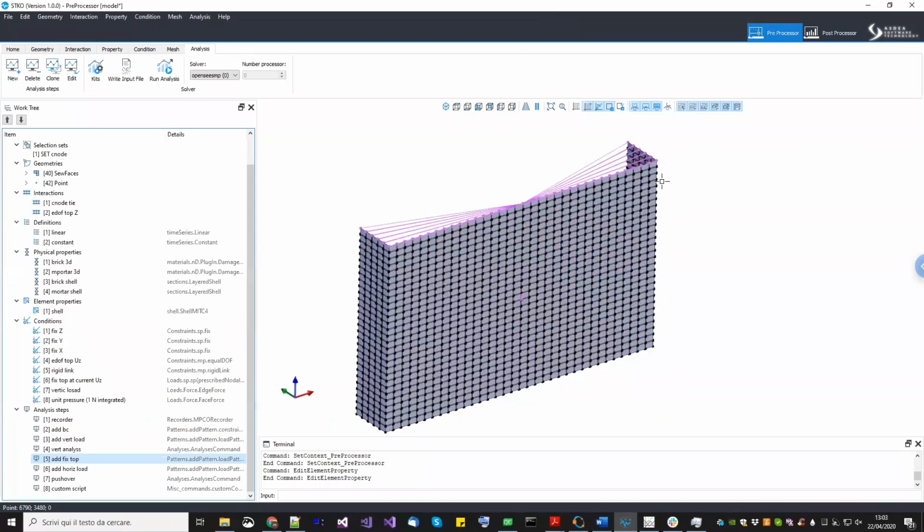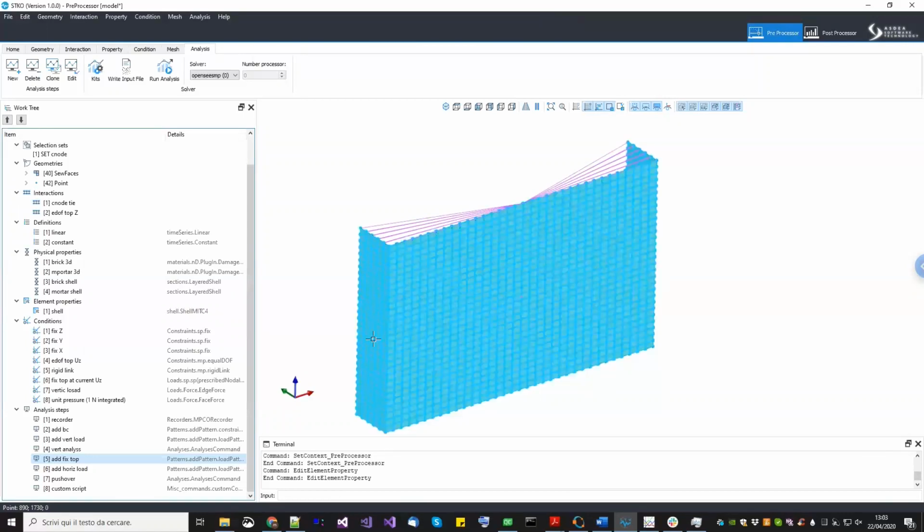Now, since we realized that in this example, even if the overall failure is in out of plane bending, the local failure is in transverse shear. Now, as you know, material models such as frictional materials, such as the one that we use in the mortar, have the phenomenon of dilatancy. So when it is loaded in shear, it uplifts and creates an apparent increase of volume. What's the problem is that in this case, since the vertical displacement is fixed, while the mortar joints are failing in shear, they would like to uplift the wall, but the wall cannot uplift, so it will create a vertical reaction, okay?